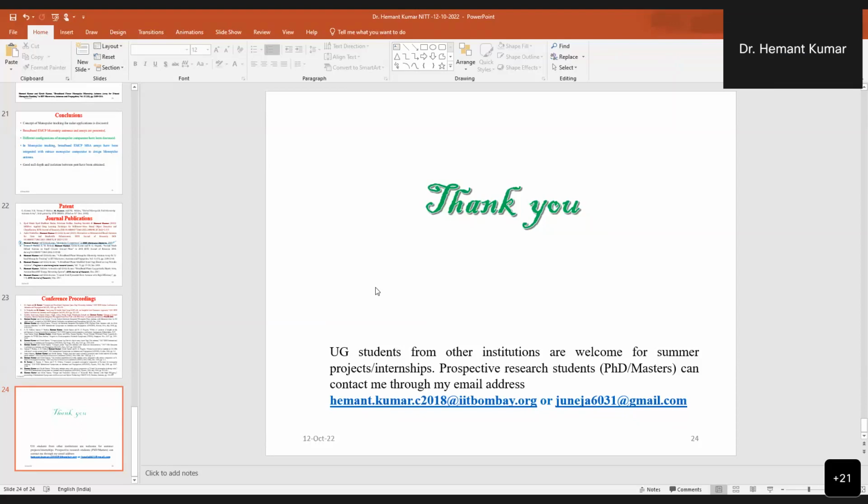So actually, for increasing the bandwidth as such in MIMO, I won't be commenting. But for increasing the bandwidth of the patch antenna, there are so many techniques available in the book Broadband Microstrip Antenna by Professor Girish Kumar or Professor KP Ray. In my presentation, I used EMCP, but there are other techniques: gap coupled, inverted EMCP, and direct coupled. In that book, 2 or 3 chapters are totally based on techniques for increasing the bandwidth. You can check that book for increasing the bandwidth of your patch.